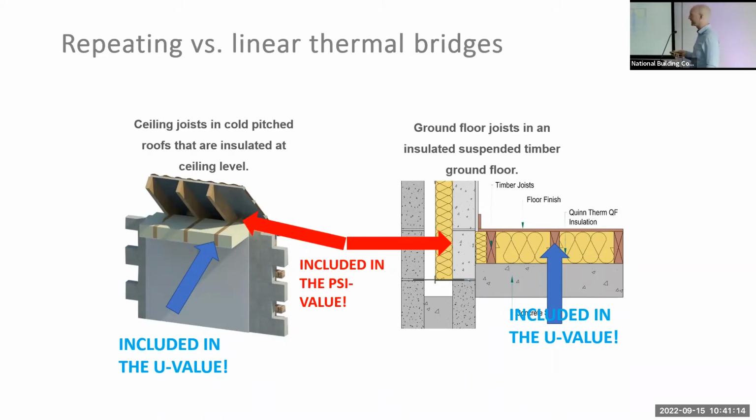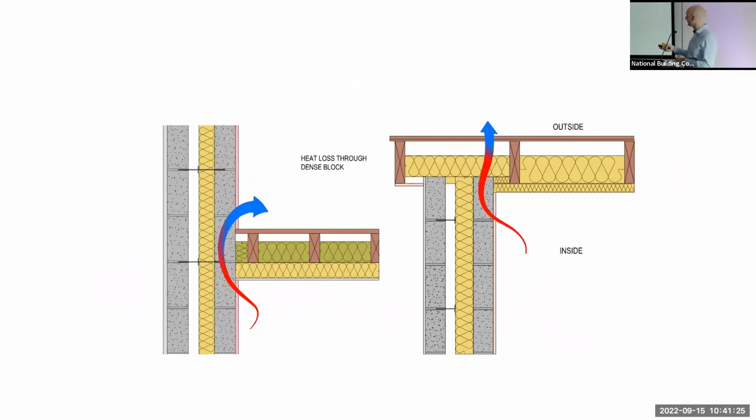So you'll often hear people talking about passive house being free of thermal bridges. It's thermal bridge free construction. It's not. It's just that the way they measure the building means that the way we account for the energy losses will result in negative psi values if you were to count them. But if you were to do a Y factor calculation on a passive house in accordance with Irish DEAP conventions, you'll still get a very, very good Y factor, but it will be a positive value. So you only get negative thermal bridges because in passive house we measure the building externally. And we'll talk about that now in a second, how that pictorially happens, what it means.